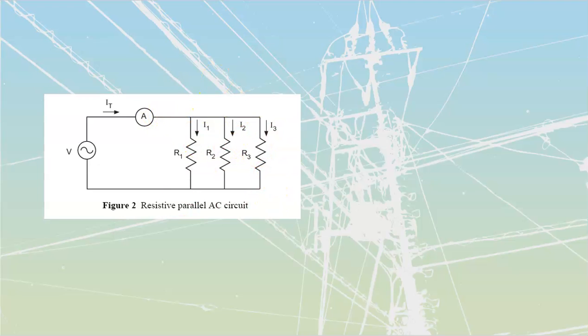We also know that we're going to be working with KCL at this point. KCL is Kirchhoff's current law, which states that the sum of all currents that enter a node, any junction, has to be the same as the currents that are leaving that node. So if I take a look, I've got the total amount of current that enters into this node over here. And then coming out of that, I've got I1, and then coming out over here is going to be my I2 plus I3.